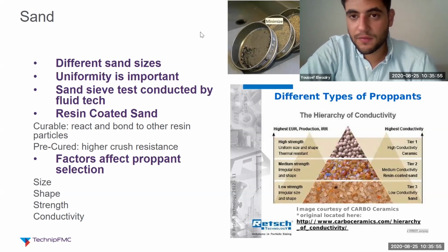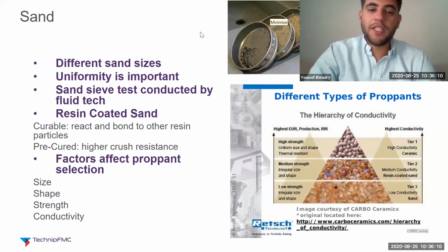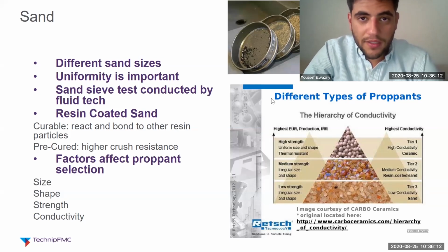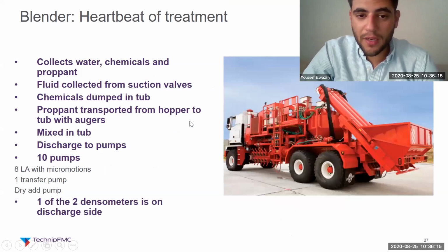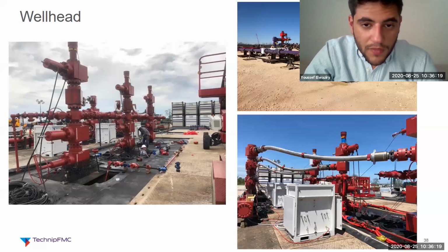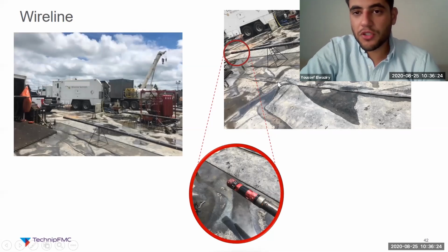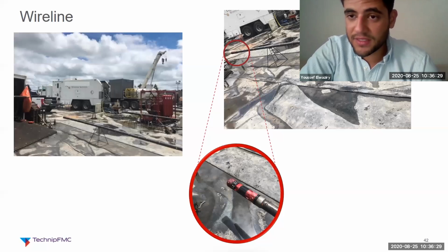Okay. The next question, do they use only wireline tools to set up plugs and perforate the pay zone, or can this operation be done by other service segments? It's a good question. The wireline we are talking about here is usually used for plug and perf. This is usually done before frac gets there.